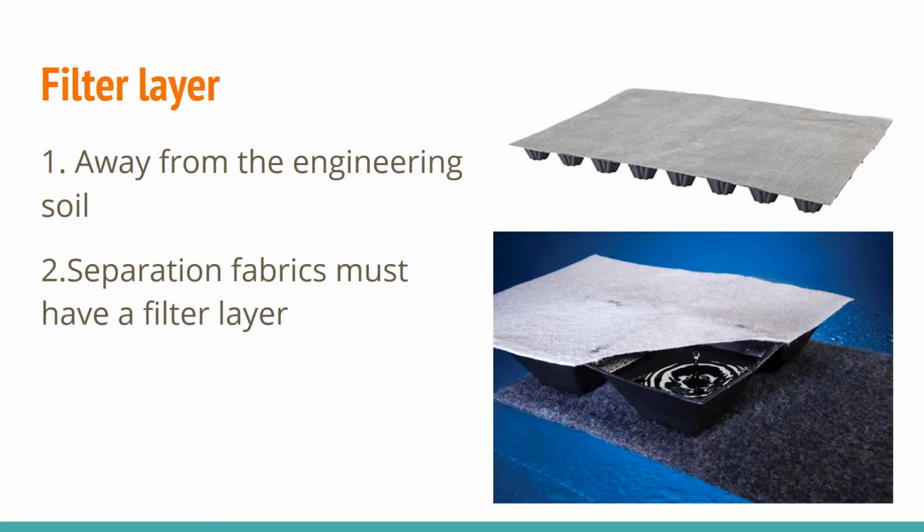Then I will talk about the filter layer. The filter layer should be placed above the drainage layer to ensure the normal operation of the water storage and the drainage system. And separation fabrics must be used as a filter layer to prevent clogging from the soil.